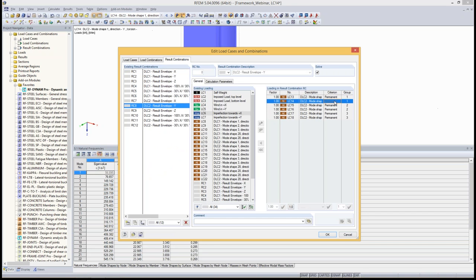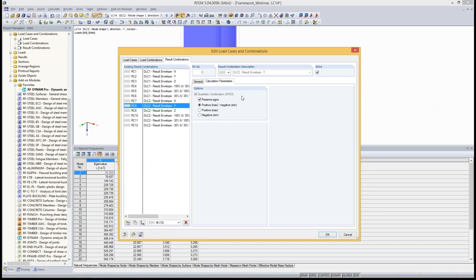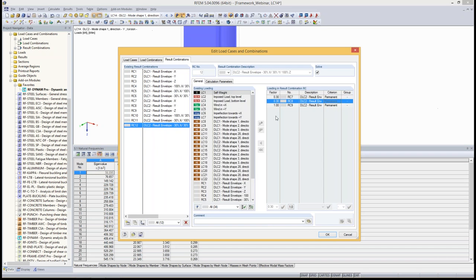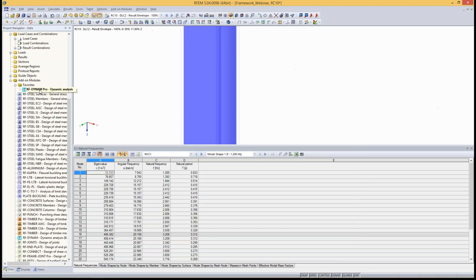So the plus torsion and minus torsion load cases are in one group, which means they are combined with an OR combination first, and then the SRSS rule is applied as we explained it earlier. So the second step is just the same. It's using the factors, the 1 and the 0.3, as we discussed earlier. So this actually happens with the accidental torsion.